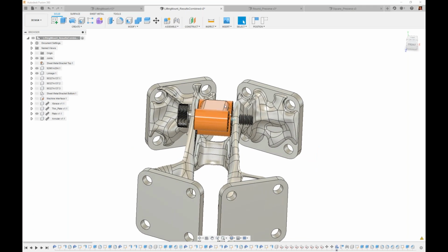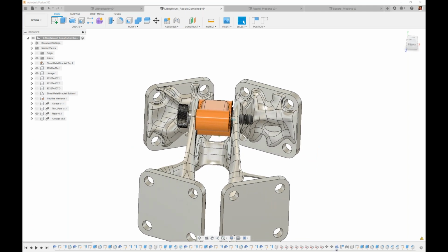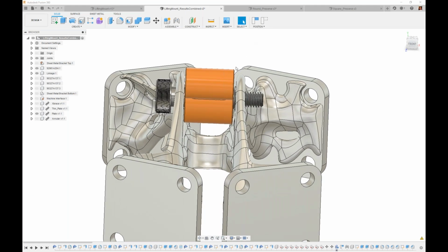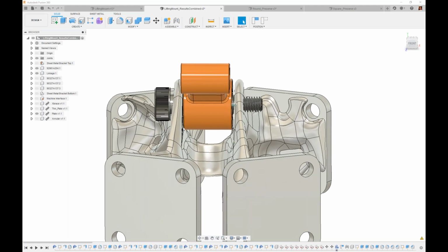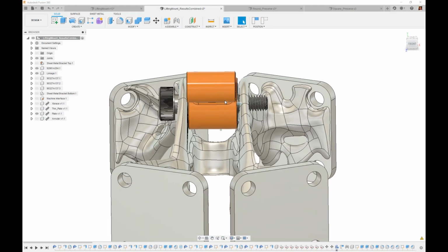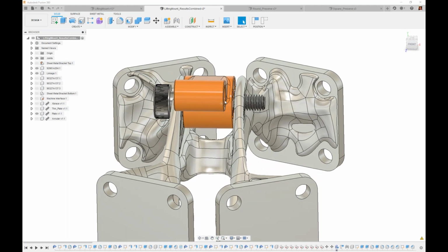Having an oversized obstacle left to right just means that now if I were to do an interference check, I know that I'm not going to have any interferences between my parts. So in some cases, it's not just for the benefit of potentially ignoring the final cutout step, but also just for clearance aspects, right?